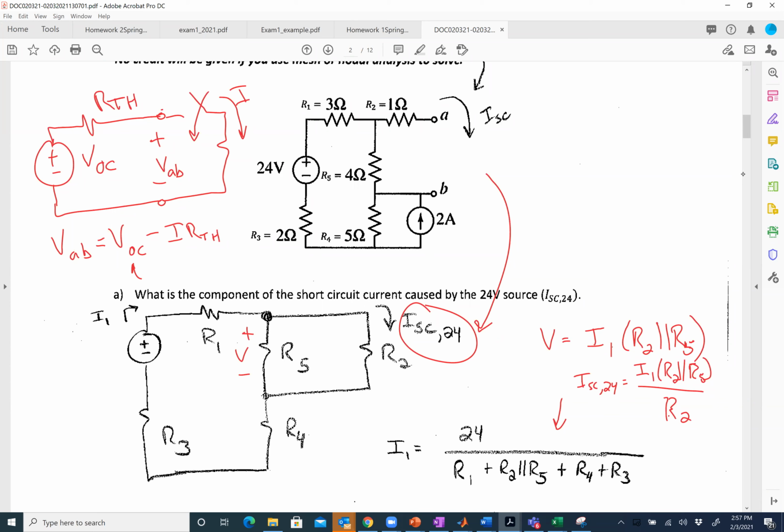So, you can sort of separate them that way. And this totally happens. If you look at a voltage at an electrical outlet, if you connect a load up, all of a sudden that voltage will get smaller once you start doing it, because now you're pulling current through all the resistances that are in the wall wiring. Does that make any sense whatsoever? Yeah, it did. At least to me. At least to Eli, at least to one person.